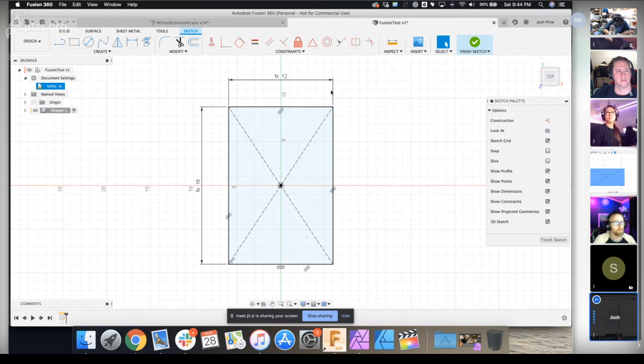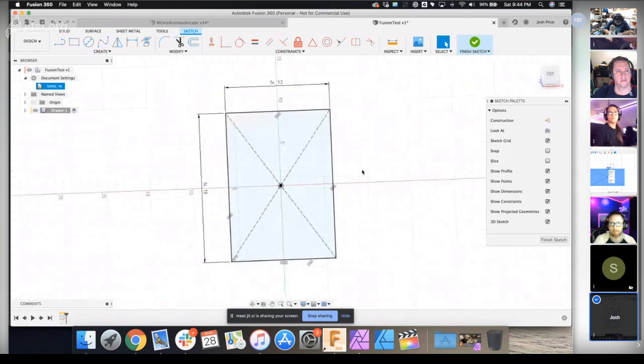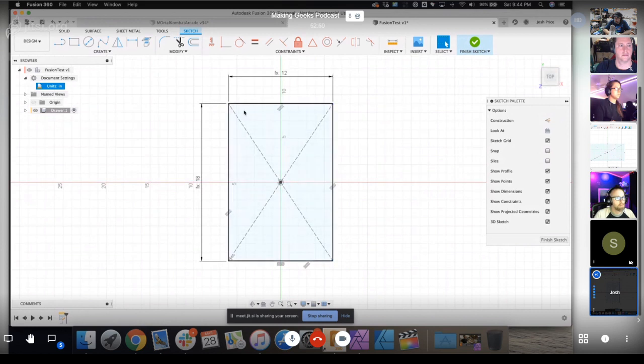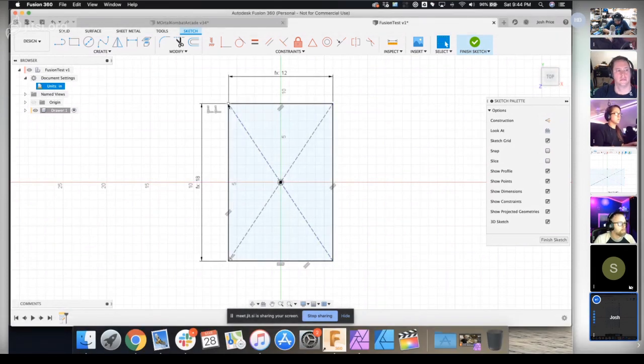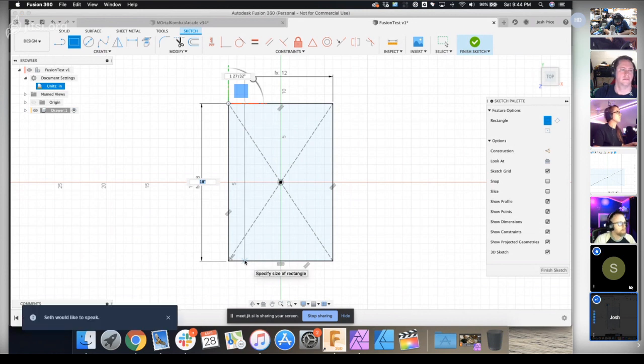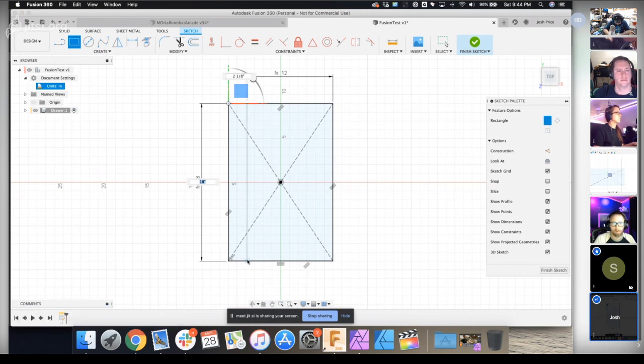Now we're going to build the walls to our box, and then we're going to pull them upward. You can move it if you want to. I'm going to create a rectangle. But because I'm going to make a wall, I'm actually going to start here in the corner. So I'm going to use the rectangle that's up there at the top. I'm going to start there, and drag it down. Now, a lazy person could say, well, I could just snap it down there because it's already on this thing. That's true, but we're going to use variables. So this is the drawer depth.